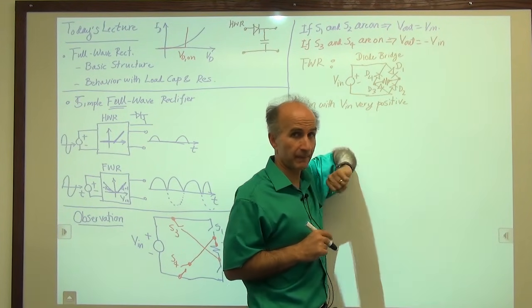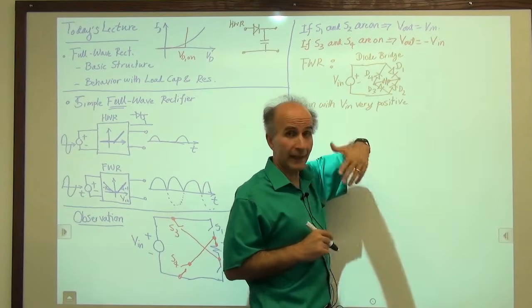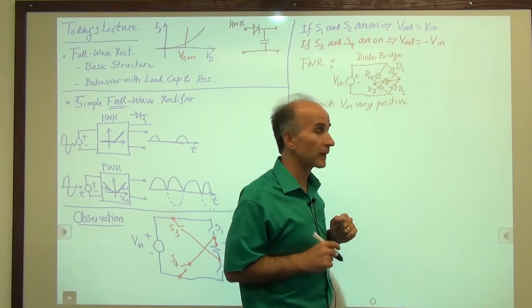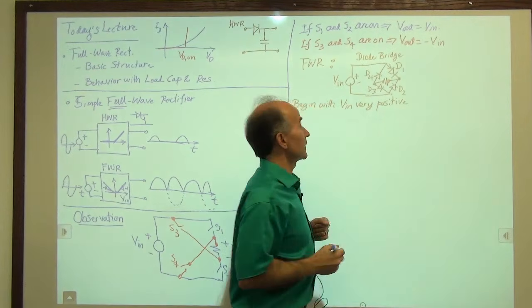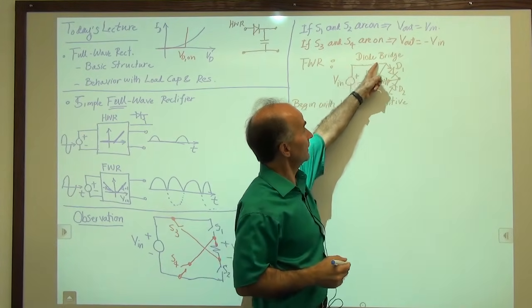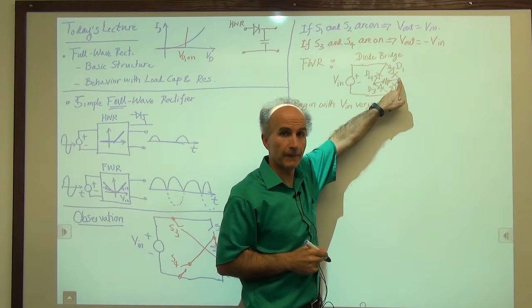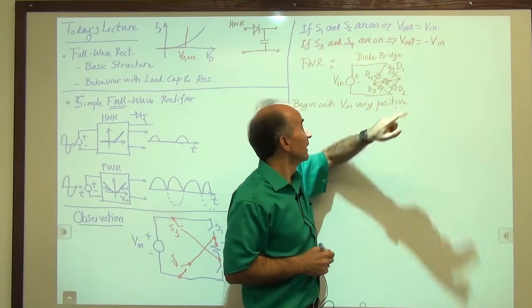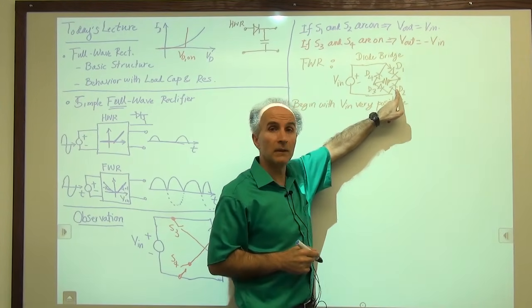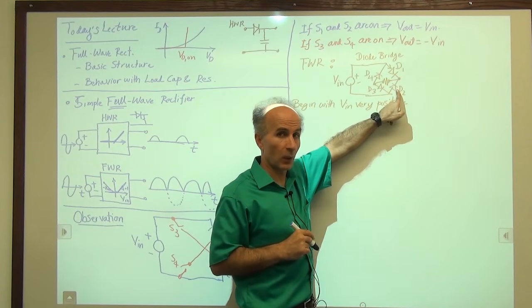That's just a guess. All right, so if D1 is turned on, it carries a current. So here's the current flowing through D1. There's a current coming out of the voltage source, going through D1, arriving at this node. The question is, which way will this current go? Does it go this way? No, I'm thinking that D2 is probably off. Why?